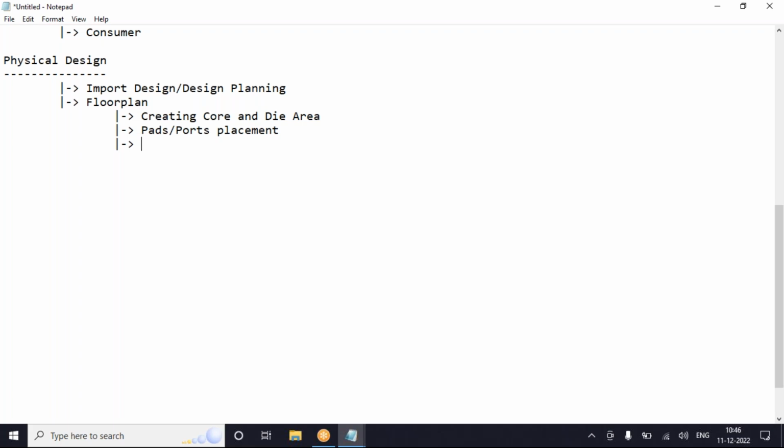And after that, I've got the interfaces. After that, I'll be deciding what are power hungry, and I'll try to start placing them. Macro placement. After macro placement, standard cells come next, not now.